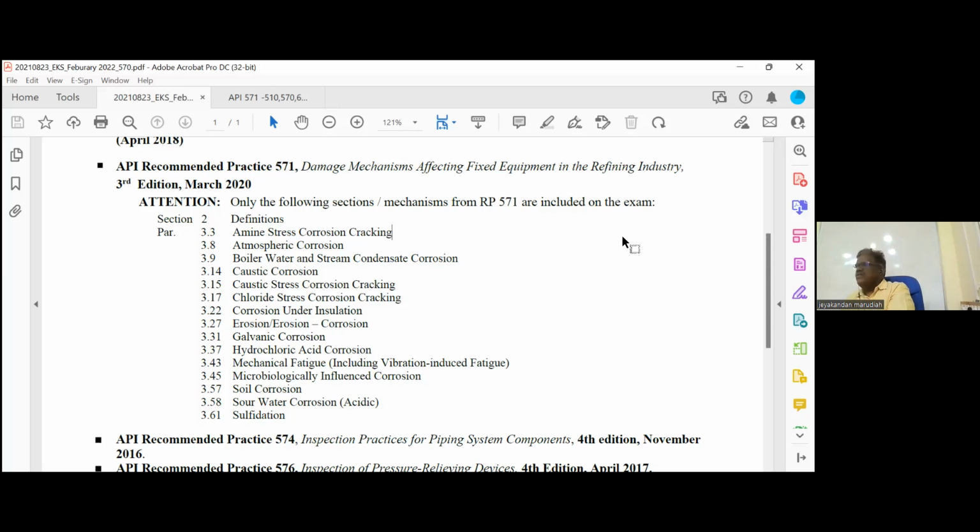But the acoustic emission principle is that when any crack develops or any part deforms, it will emit some sound. For example, if you tear a paper or a glass is broken, it will emit some sound. If you can pick up the frequency properly, you can detect the length of the crack, from where to where it starts. That is called acoustic emission testing. Now, the question is, how do I know when the crack will start?